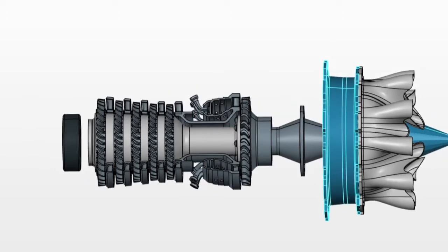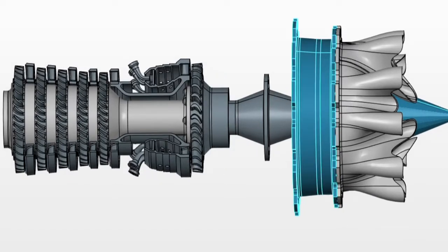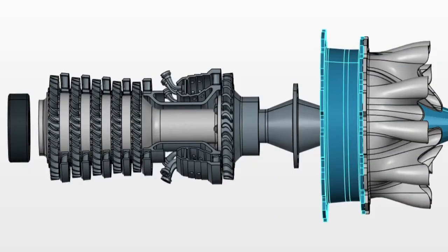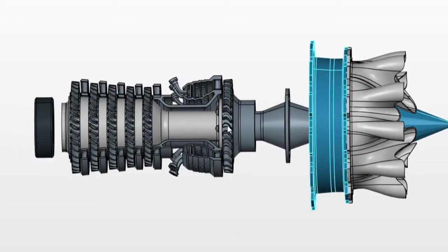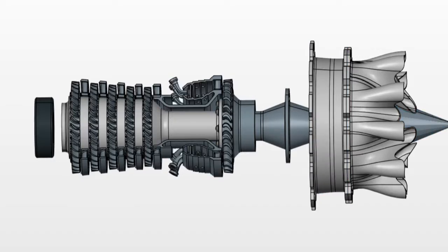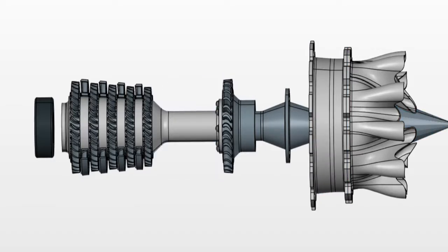This final engine component is the turbine. As high-pressure air exits the combustion chamber, it spins the turbine. The turbine and the compressor blades are connected on the same shaft, which runs right through the combustion chamber. So, the energy that the turbines gain by spinning goes back to powering the compressors. This is essentially like placing a fan in front of a wind turbine and then having the turbine power the fan. All that is needed is a steady flow of wind, and the system will power itself.